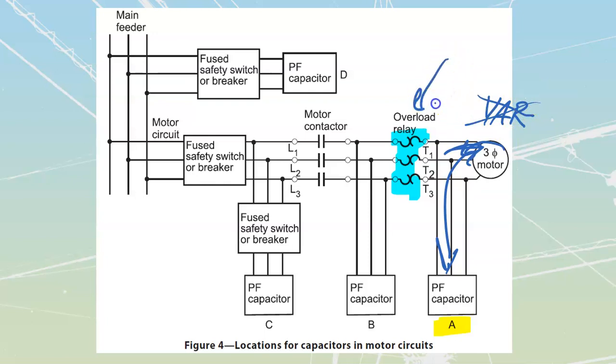So I'm going to have to be careful with these, and I'm going to make them smaller. I'm going to have to do this through just doing some testing, running the motor with an ammeter on there, and figuring out what size I should be using. It can be a little bit tricky to do. And because it's a little bit tricky, equipment manufacturers don't like us doing it, because there's a chance that we could screw that up, burn out their piece of equipment, and then come crying back to them for warranty. They don't like that.